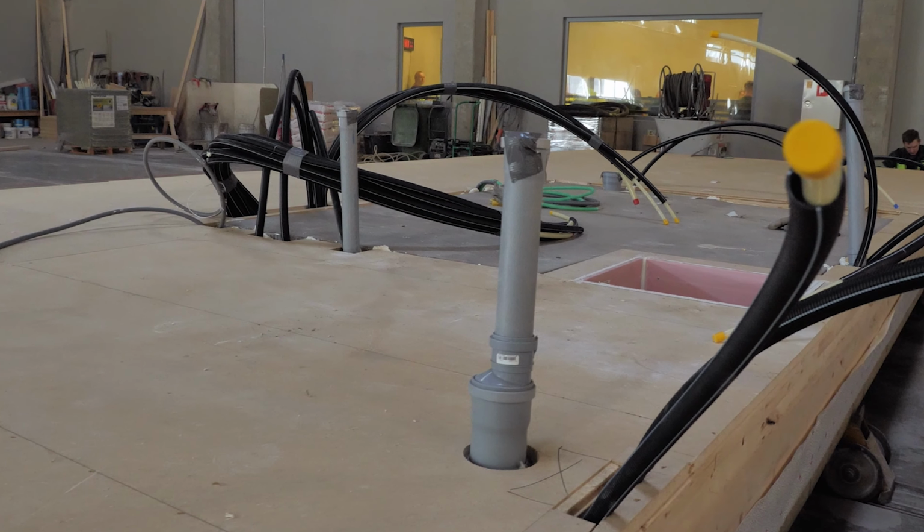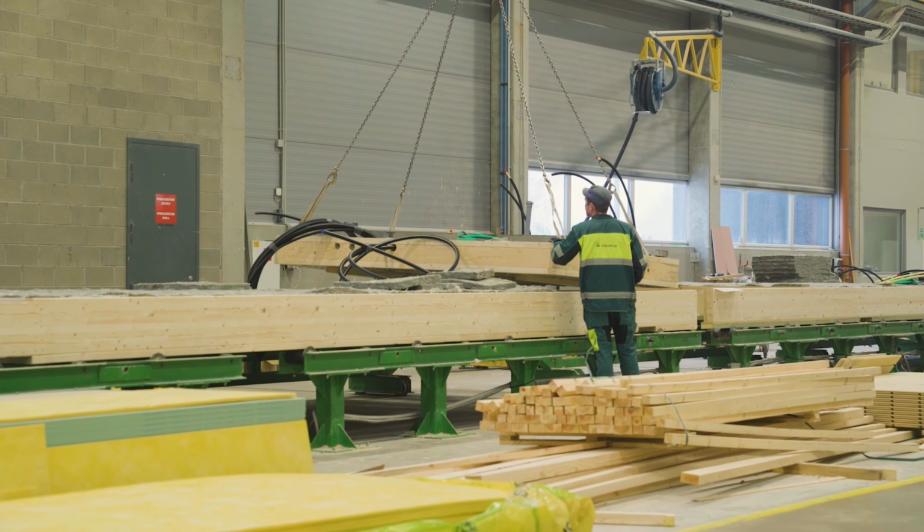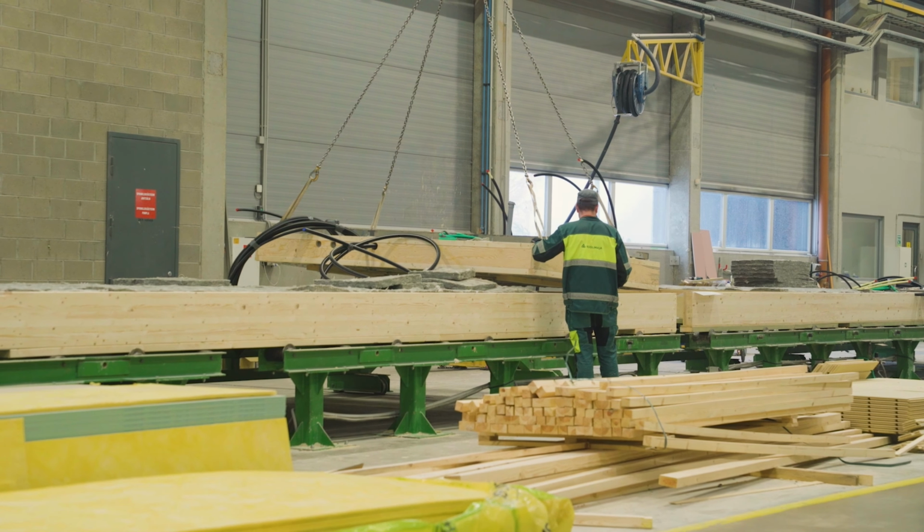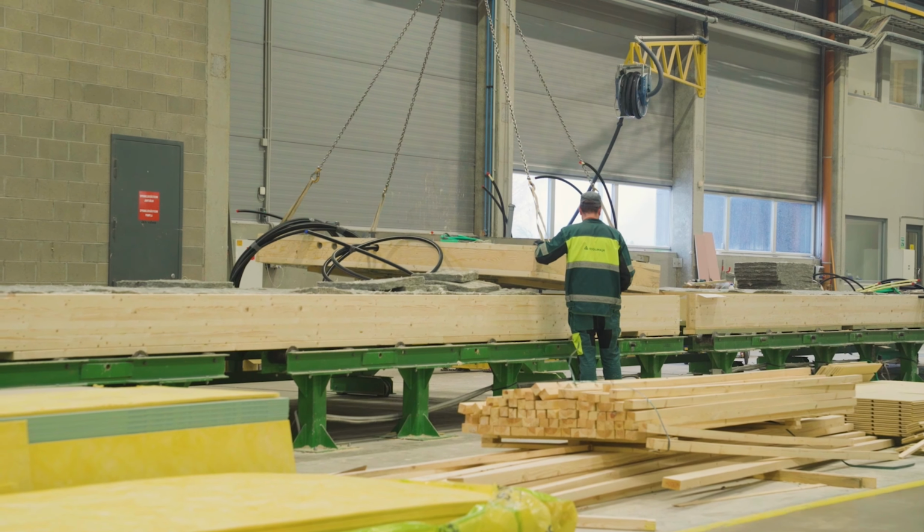The sides of the shaft openings in the floor panel, in the case of multi-story buildings, should be constructed according to the project documentation, typically using plasterboard, and the joints are sealed with fire-resistant sealant. In case a specific floor section for a wet room is included in the assembly, it should also be installed. Some companies, especially in modular building, prepare wet room floor sections separately, with the required floor slopes and heating system in the floor element. This kind of solution will later help to speed up the work done in the module.